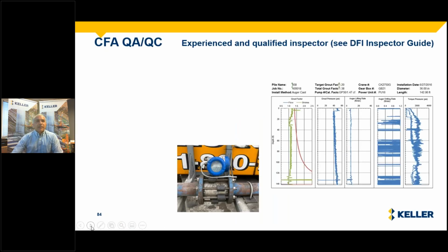On the QA/QC, which has been evolving, we have inspectors on the site to review and certify that everything is done correctly. Now, with the use of computers, that inspector can also have an iPad or similar handheld device to get the readings from the equipment and verify what's going on. We have flow meters that measure how much material we're installing and at what depths. Total material installed is the red line. Material per every foot or every meter is measured here. What was the pressure when installing it? Was the speed of installation fast or slow when we're pumping, and that translates to quality.